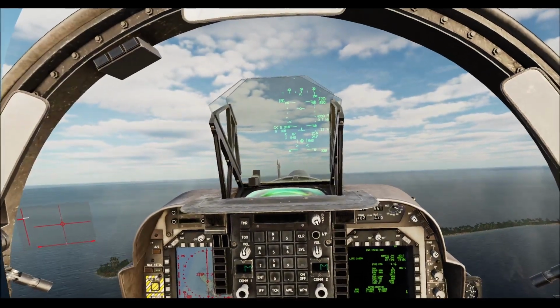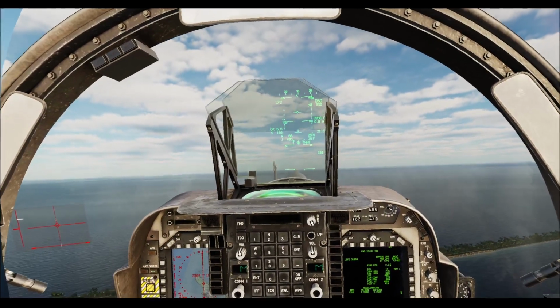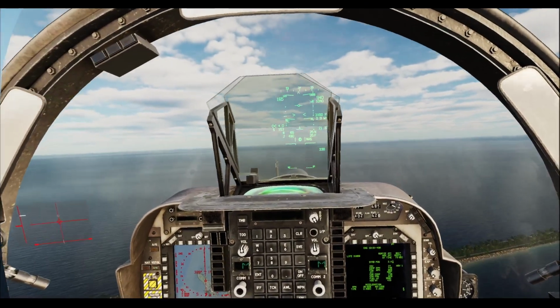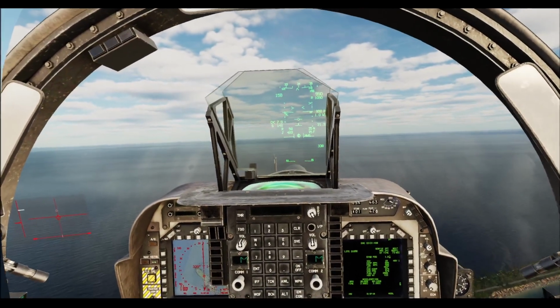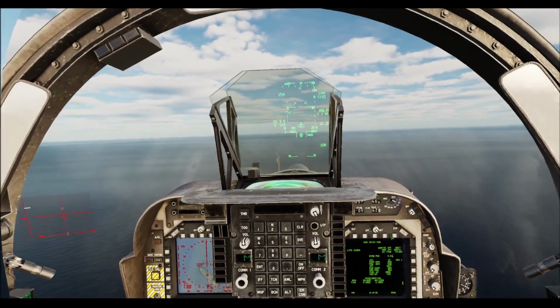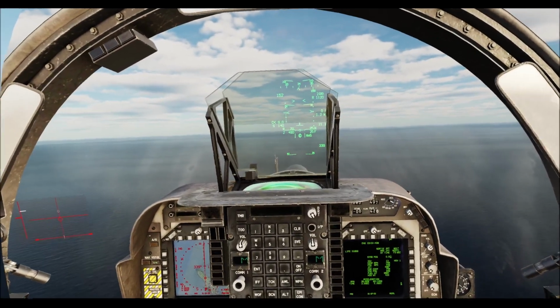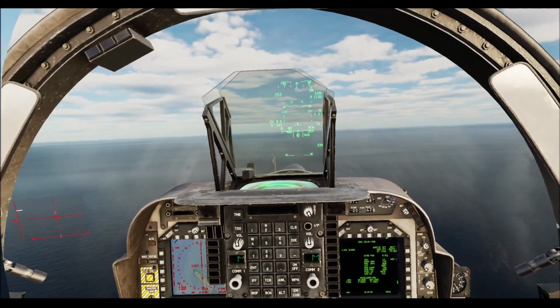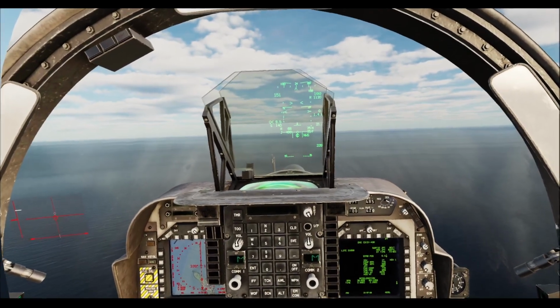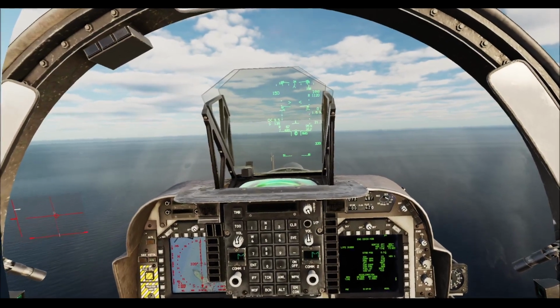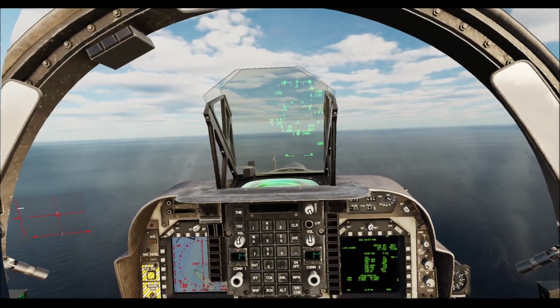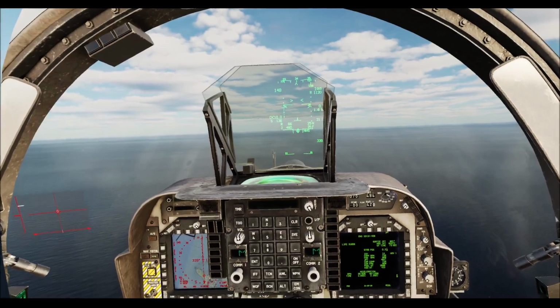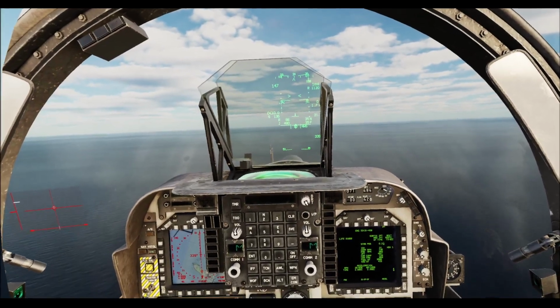Don't let the aircraft climb away from you too rapidly, because then as soon as you level out, you'll pull the power back and the aircraft will start to descend. Adjusting the power upward to keep AOA and straight and level. And slightly bring the power back and trimming nose up. Still trimming nose up. There we go.